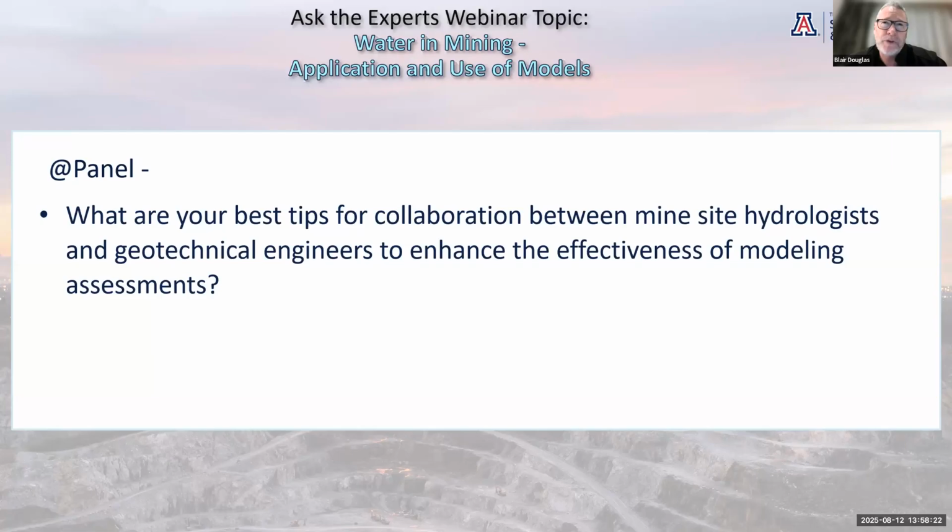And the second thing we really need to push them on is to make sure they demonstrate the sensitivity of pore pressures, and that you work through depressurization effects to see what is required to bring it back in line with stability, and whether or not you can. And be realistic about it, and make sure you then set together trigger action response plans, TARPs, which you both agree to based on the science that you have at the time.